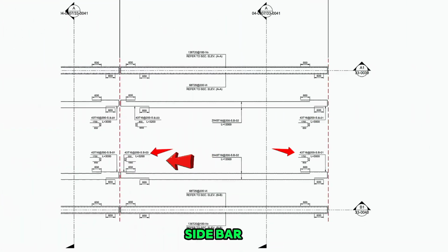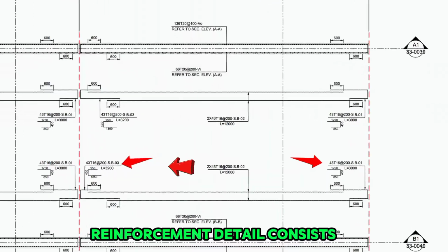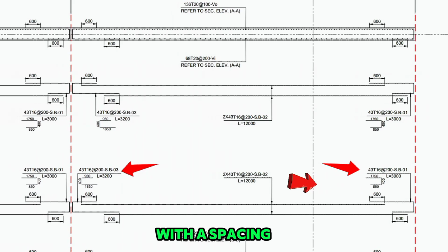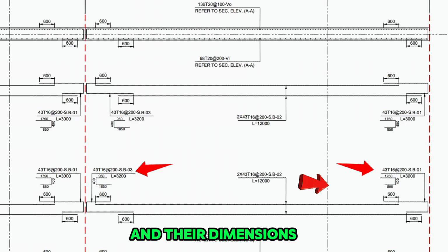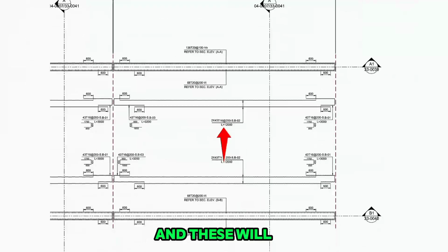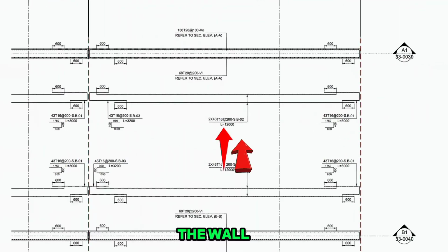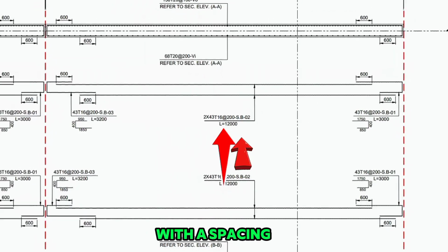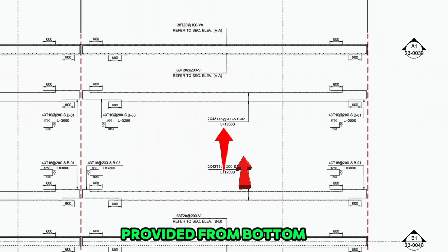The tunnel wall side bar reinforcement detail consists of 43 pieces of 16 millimeter bars with a spacing of 200 millimeters, and their dimensions have also been included. One length is longer and one is shorter, and these will be provided on both sides of the wall with 43 pieces of 16 millimeter steel bars with a spacing of 200 millimeters provided from bottom to top.